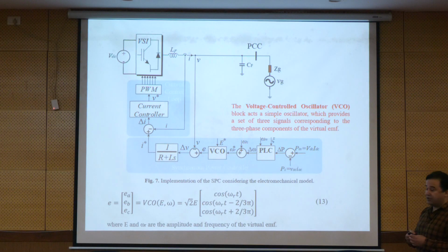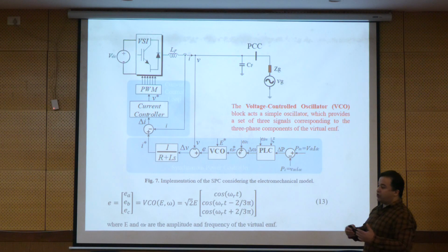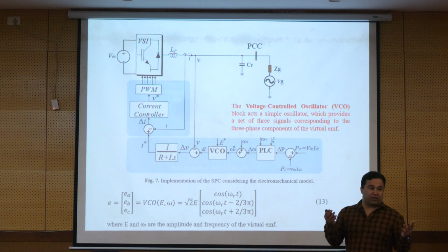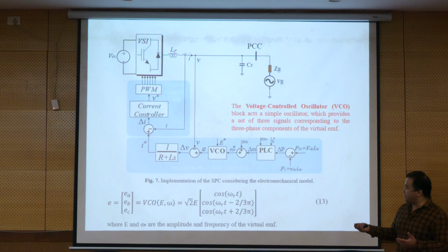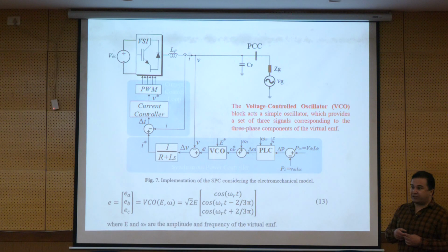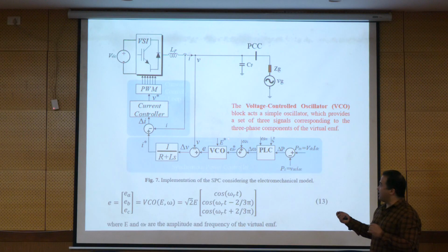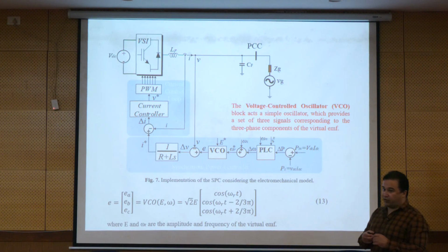or the output of the converter. You know that the converter is going to be connected to the 400 volt grid, so you know the value of the reference voltage. By this, you can provide the three-phase system with 120 degrees for each phase. Is it clear? This is not something complicated. Probably the calculation of the delta omega is a little bit challenging, but for this we just have the omega R and E. Based on that, we provide the reference value for the output voltage of the converter.